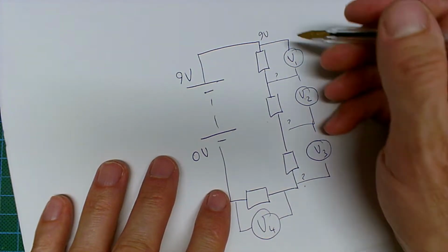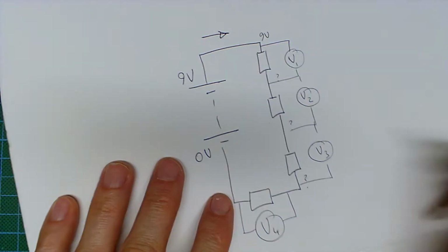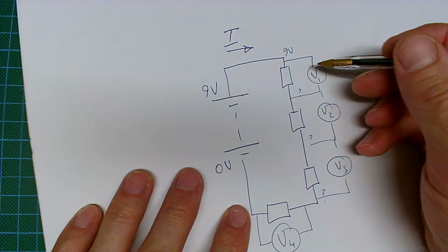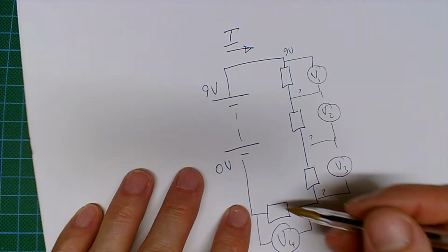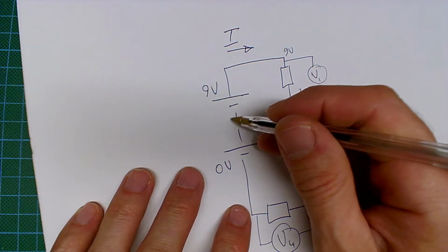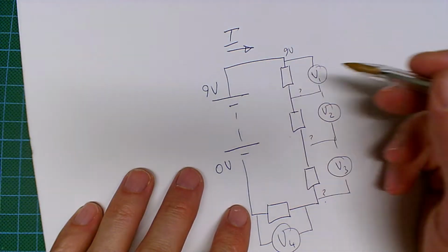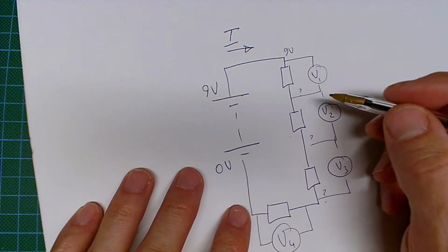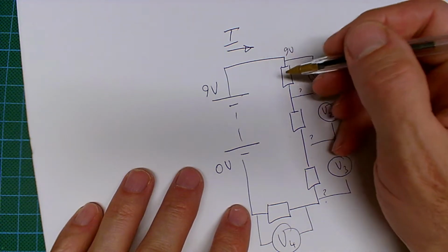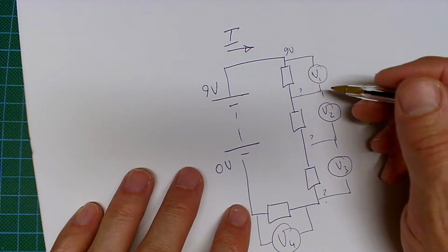And the reason for that is that the same current is going to flow around the circuit, the same current going all the way around. So we don't have to say like I1, I2, I3. It's the same current that flows through. It's a little bit like water being pumped around with the battery being the pump. So the same current is flowing around, but each one of these could potentially have a different resistance, and so it will have a different voltage drop.